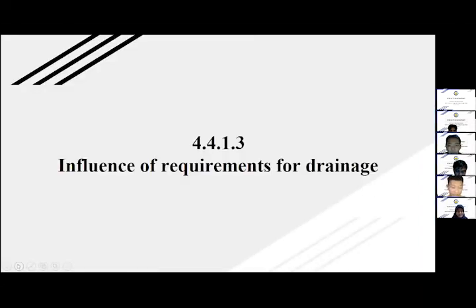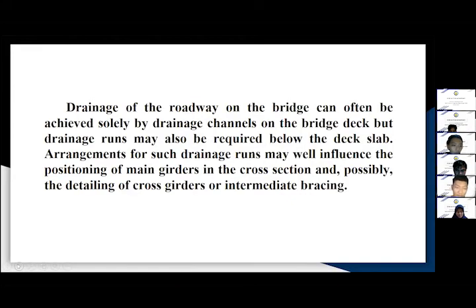Influence of requirements for drainage. Drainage of the roadway on the bridge can often be achieved solely by drainage channels on the bridge deck, but drainage runs might also be required below the deck slab. Arrangement for such drainage runs may influence the position of main girders in the cross section and possibly the detailing of cross girders or intermediate bracing.